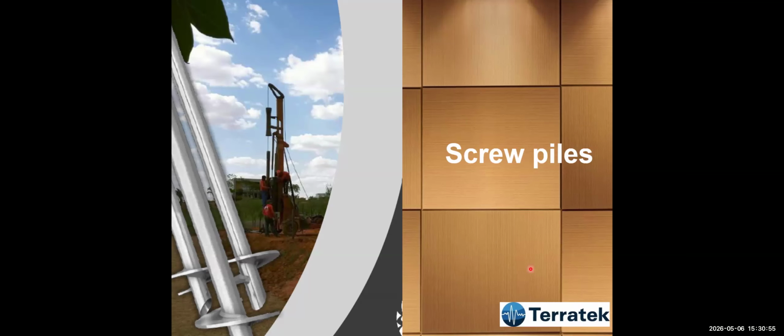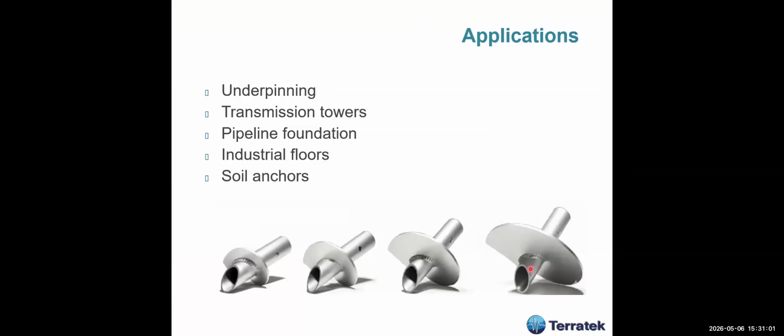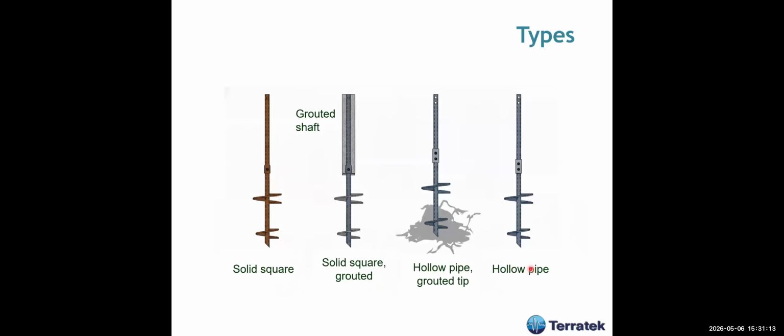Let's discuss screw piles. Screw piles, well, I've been using them in a few projects, and their main applications are underpinning, transmission towers, pipeline foundations, industrial floors, and soil anchors. Sometimes they can be very, very helpful. So these are different types of screw piles.